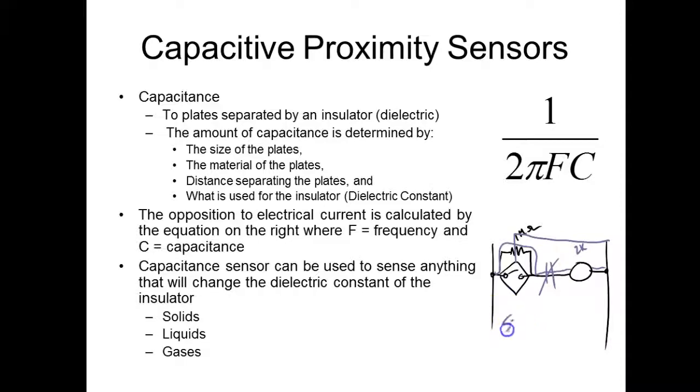And they're called solid state limit switches. And we have two types of solid state limit switches. They're either going to be capacitive, or they're going to be inductive. What does a capacitor sense? What can they sense? Anything. So these definitely have a little adjustment on them to set the sensitivity, so you can decide what it senses and what it doesn't sense, right? But once it trips, it'll sense everything above that, right? Y'all understand that? Yes or no?